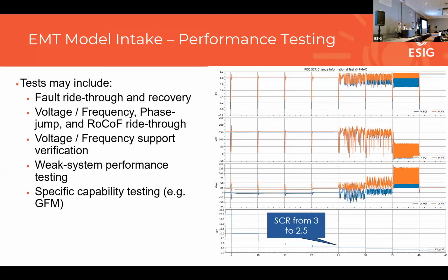You could take those curves and play them into the model and get a feel for whether the model is going to ride through and perform acceptably for that voltage or frequency profile. And we can take that to the next level and do phase jump testing and even rate of change of frequency testing as well in our simplified system.